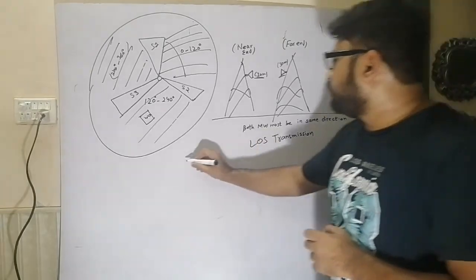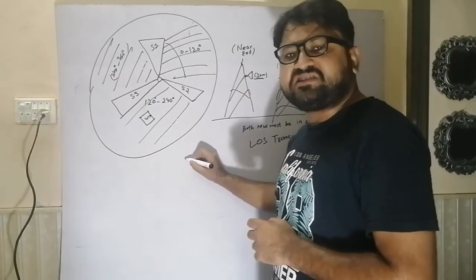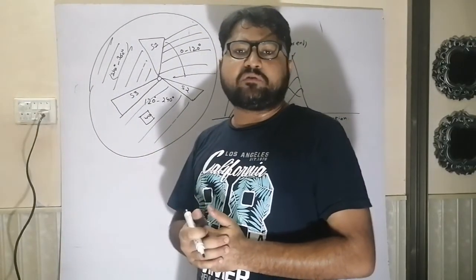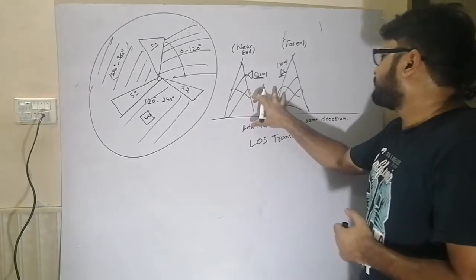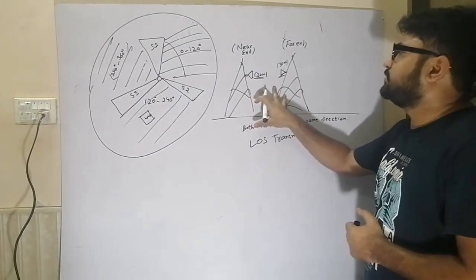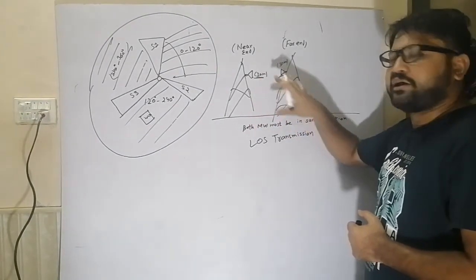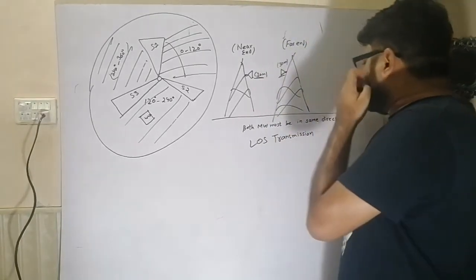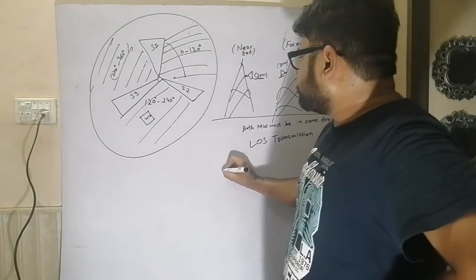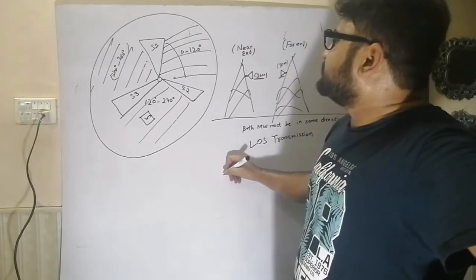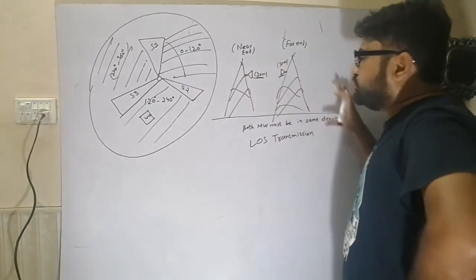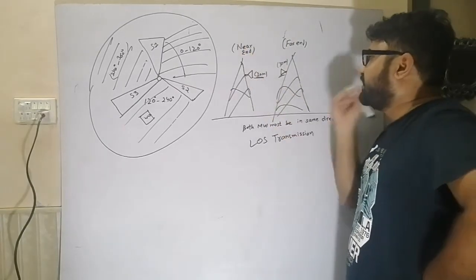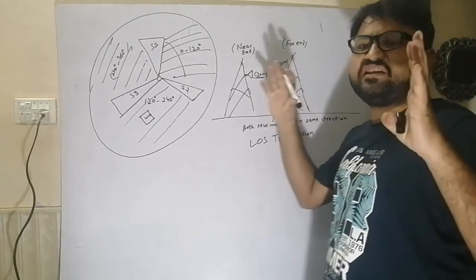As you know, for a fixed network we have media like coaxial cable and copper wire. But in this microwave transmission, which is wireless transmission, we have microwave antennas, and between them the medium is air. So in a survey series, you need to check sector-wise the orientation and direction of the antenna, and that the microwave antennas are facing in the same direction.